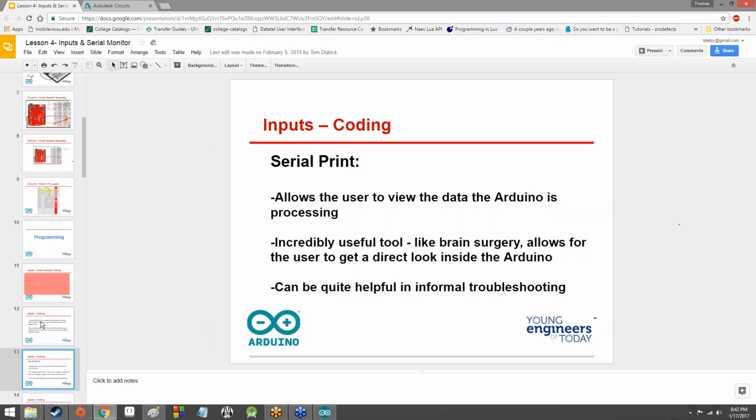Well, let's test out the serial print and see if that doesn't illuminate what the issue might be. Because it's such a bare bones little framework, it's basically just a means to an end so the Arduino can send some information out to the computer and we can look at it. It means that we can customize that information that's sent however we'd like.